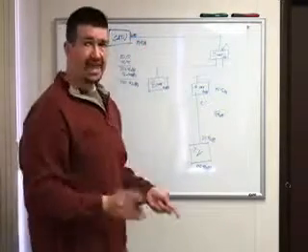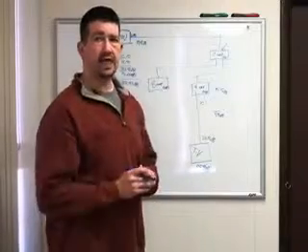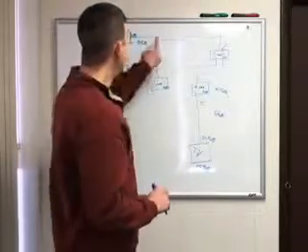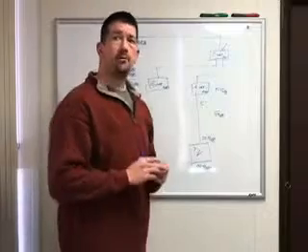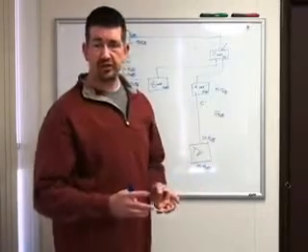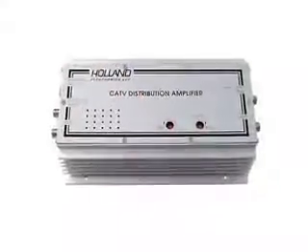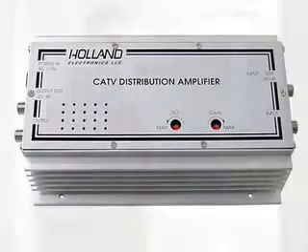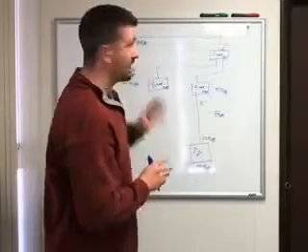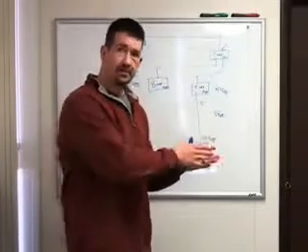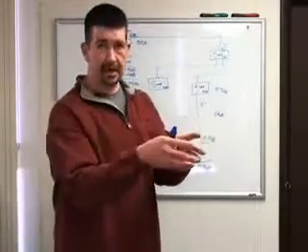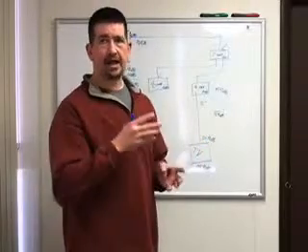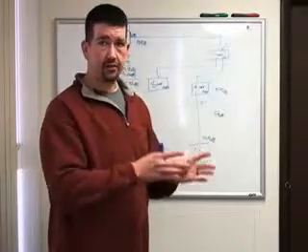So that gives us the gain of the amplifier that we need to have to put in place here. So what I'm going to recommend in this case is that we get a 30 dB amplifier which has a 10 dB adjustable gain on it. Now what that means is that the amplifier can go as low as 20 dB gain up to 30 dB gain. So again, I always design things a little bit hot so I have a little bit of room to move.